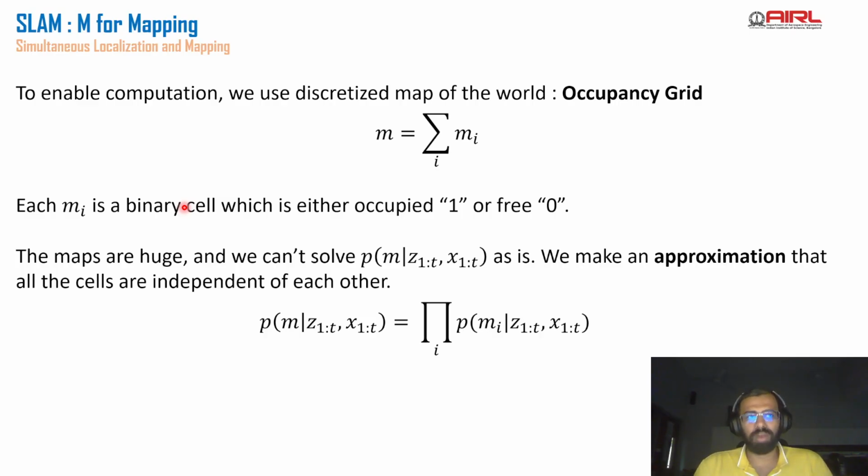Right. So before we go to something like this, let's first understand a bit of the math behind how things are happening. Now, as we did with the EKF and the factor graph SLAM, we'll assume our world to be 2D. This 2D world we will discretize into an occupancy grid, right? So each grid cell would either be occupied or free, or there is another variable which I have not really mentioned here, which is unknown, right? And we will see how that plays a role a bit later. But mainly we are concerned with: is it occupied? Is it free? That's all.